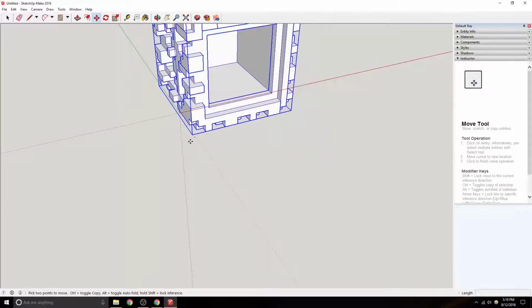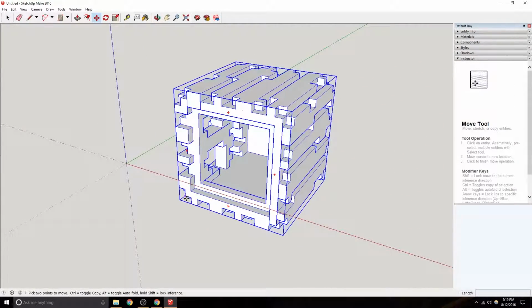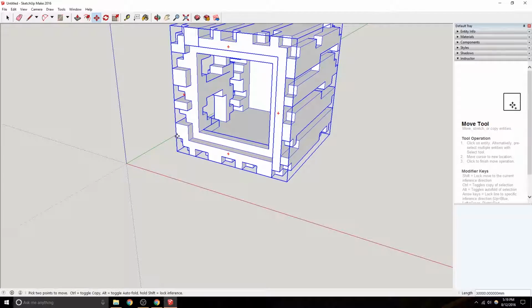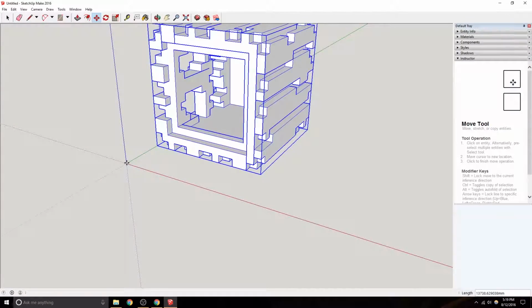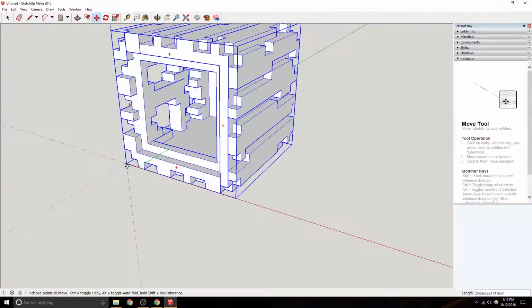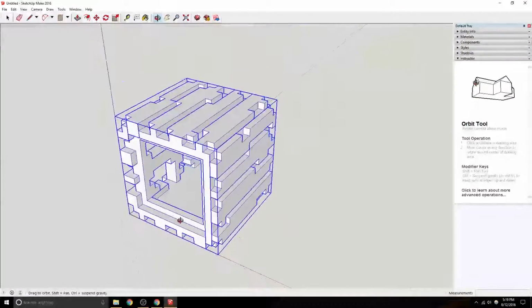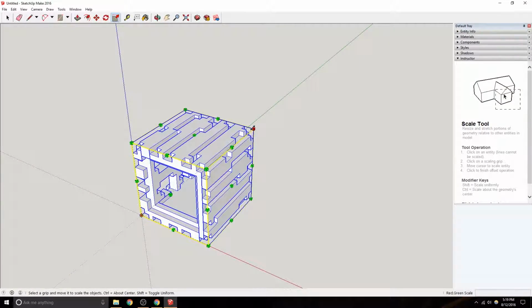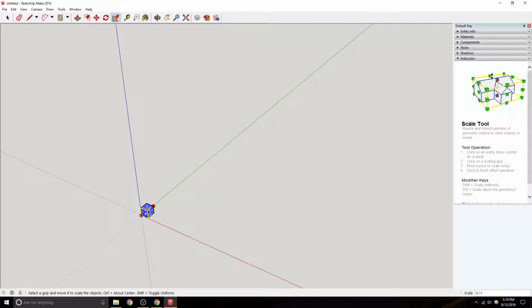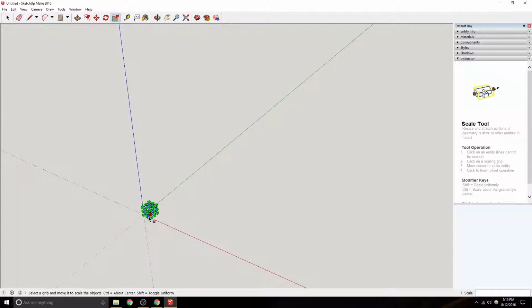This thing is going to be massive. This is the catch with a few conversion things. You can kind of set the edge on 0, 0, 0. You can do it that way, or you can move it later. If you reduce it to that origin, it makes it pretty easy to just do 0.001, so that's 1,000th, but you may not be able to get it right in place, so let's call it 0.01, reduce it to 100th, and you'll see why in a second.